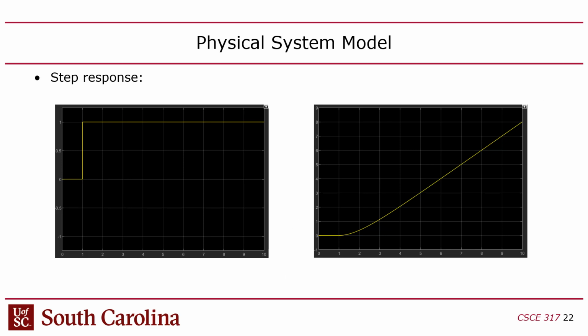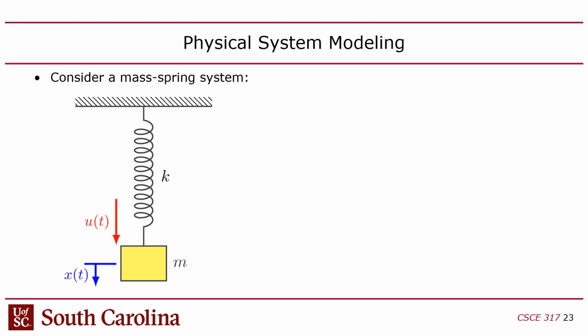So is that true? Let's say I put that in MATLAB and Simulink, and I simulate it with a step. Yeah, it is actually unstable, believe it or not, despite what I said earlier. Because if you give it a step function, that's basically like saying I'm going to set the force to 1. I'm going to give it a constant 1 Newton force and leave it there, and then the coin will just zip off into infinity. So that's unstable.